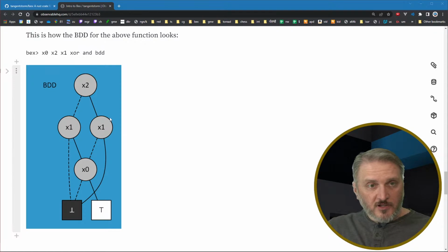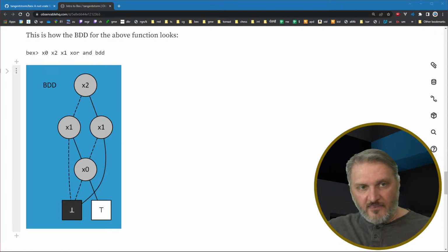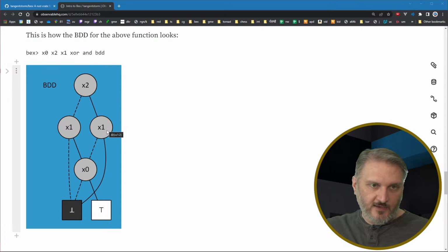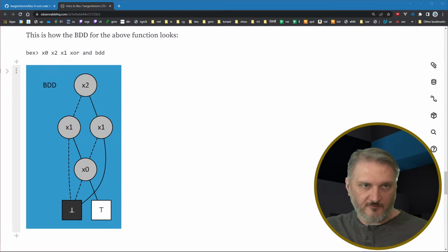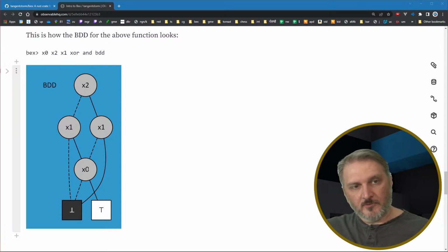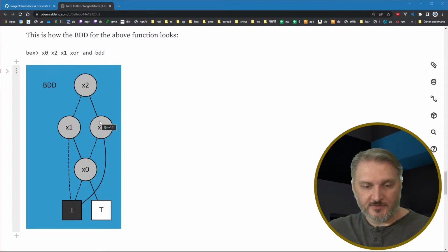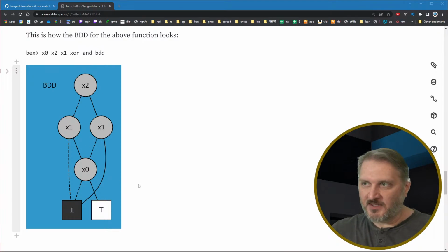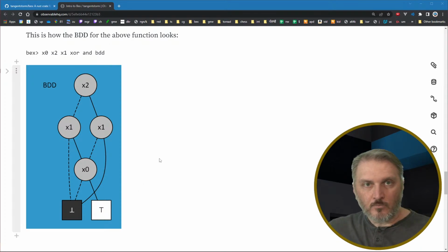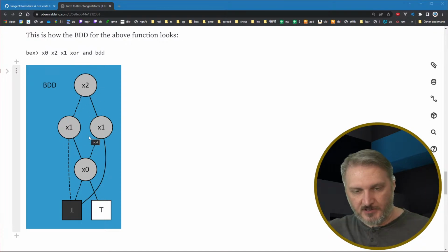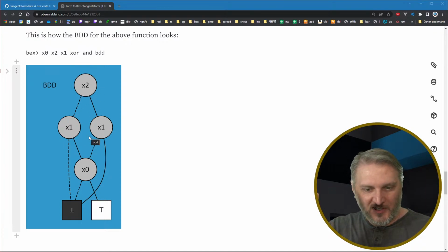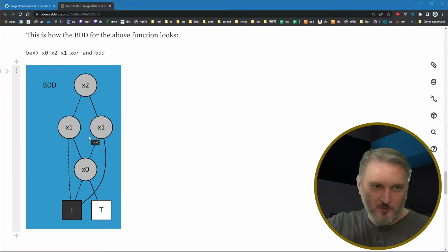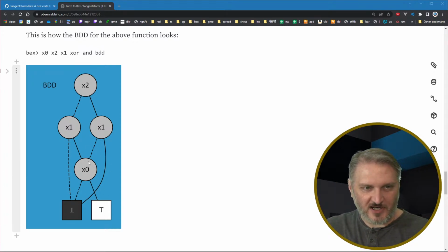You could also have the case where something is missing, and then you just imagine that it's there. So if this went directly to X0 from X2, then you would say, well, no matter what X1 is, you follow the link to the same place, but you still have to count when you're enumerating in binary, because the truth table will always be, for 3 inputs, one input would give you 2 possible values. You say, well, what happens when it's false? What happens when it's true?